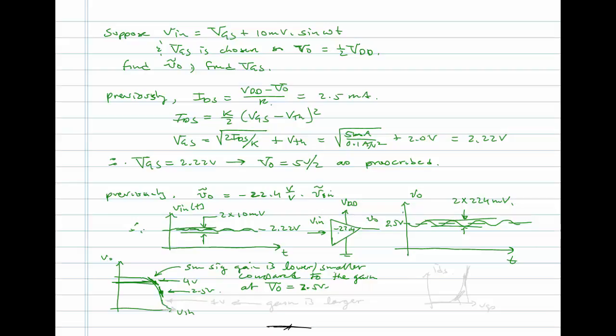Okay. Now, a trade-off would be also, you could say, well, if we made it down at say 1 volt, okay, the gain here is larger. Right? This is a square law. So since there's a square term, the higher the current is, the lower the output voltage, right? Because it's VDD minus R1 times IDS. So the higher the current, the greater the slope in the transfer characteristic. This is VGS and IDS. Right? So up here, the slope is steeper than what it is right here.